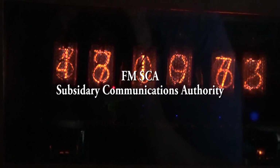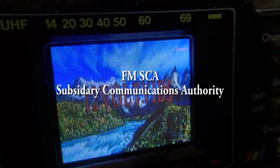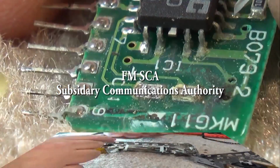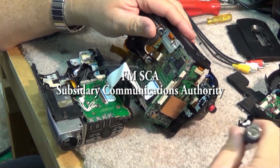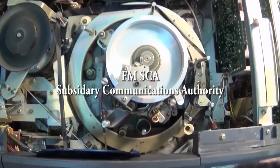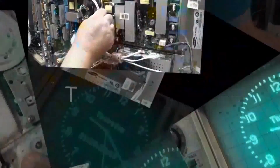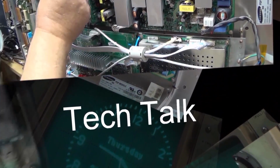Today on Tech Talk, we're going to talk about SCA. You know, the three scariest letters in radio. No, it actually means Subsidiary Communications Authority, and it was a way that FM radio stations could generate extra revenue by selling some extra spectrum that they weren't using. This has been around for years, still in operation today. Let's take a look at how it works.